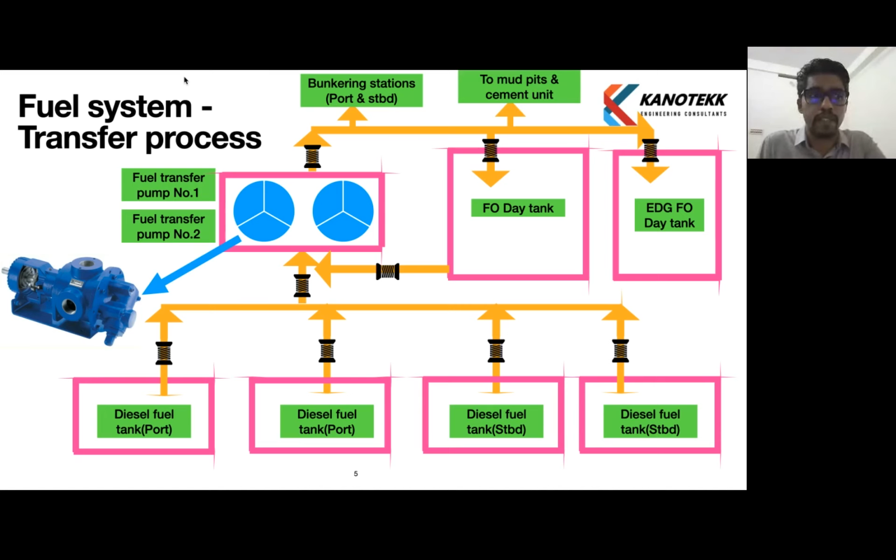Also, there will be a connection to the mud pits and cement unit. The purpose of this connection is to assist in drilling. Fuel oil is used inside the mud pits to mix with mud to change the property of the mud as per drilling conditions. Also, the cement unit requires fuel oil for operation, so there will be a tapping from this to the cement unit also.